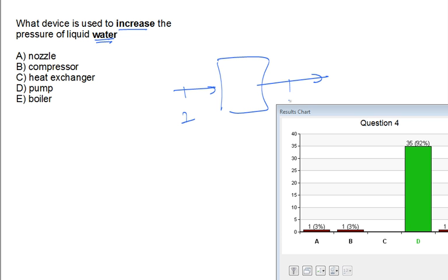Okay, I don't know what to say, but we have a beautiful section 4 or chapter 4 of this textbook where they try to do a good job of what is a heat exchanger, what's its purpose, what is a turbine, what's its purpose, what's a compressor, what's its purpose, what's a pump, what's its purpose, and distinguish between that and a compressor. They use the term pump when it's a negligible change in volume of the fluid flowing through it, but your purpose of the pump is to boost the pressure. What's the purpose of a compressor? To boost the pressure. But it's a fluid that typically gets compressed in the process. That's why they call it a compressor. I'm not trying to be tricky.